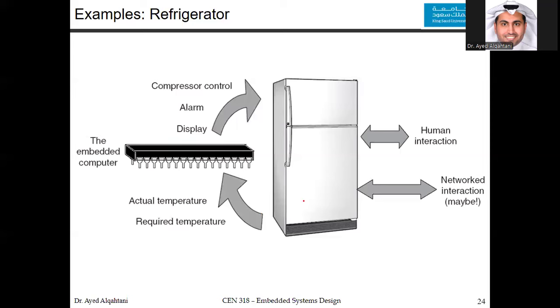Now, the assembly code is a set of instructions converted from the high-level program by an assembler. So the program, if you write in C, you use a compiler, and now the compiler will generate the assembly code for you. And the assembly code is basically the instructions. And in the beginning of this lecture, we said the difference between the CISC and the RISC. This is usually in the assembly level. In the machine code, it's the assembly instructions that are coded and flashed to the program memory in the form of zeros and ones.